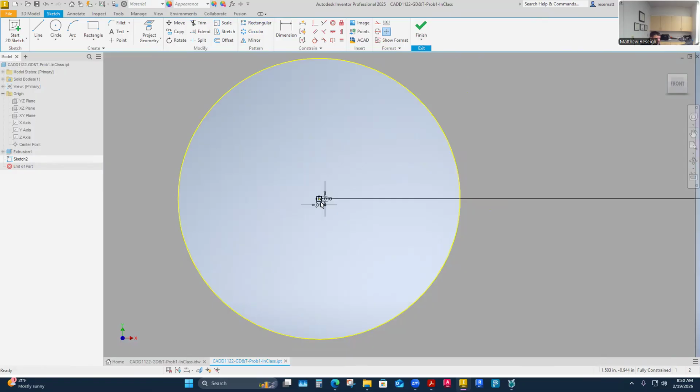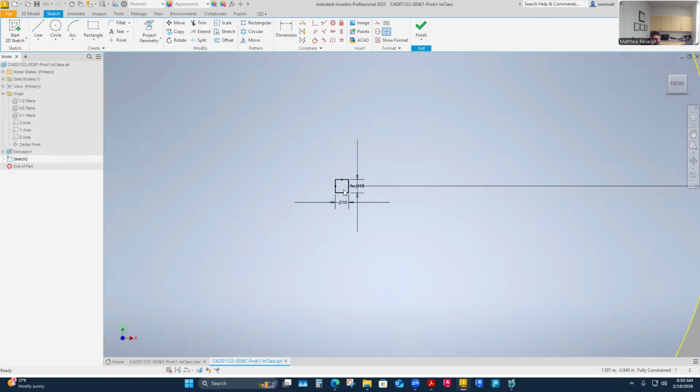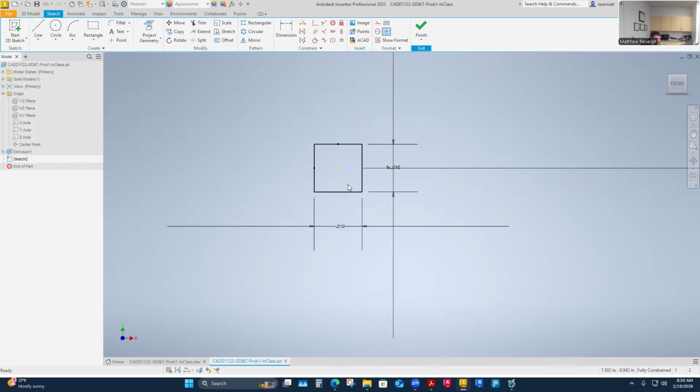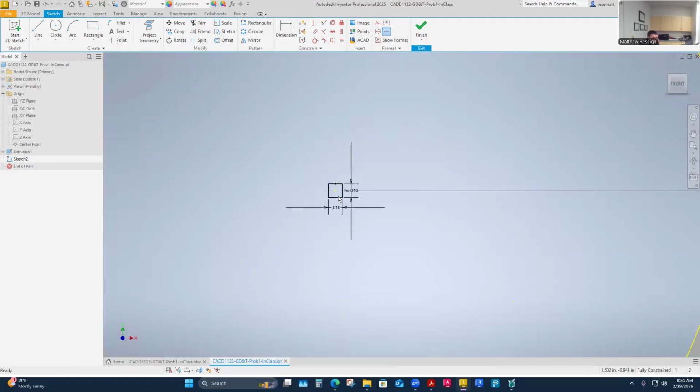So I'm saying on my drawing, if I'm the person that has to actually put the hole in this plate, you as a drafter have told me, okay, as long as I hit the center point in this little square, it's an acceptable part. If my center point falls outside of that square, it is a rejectable part. And so I build this little unusual square to have to fit my center point in. And so let me see where I want to go from here.